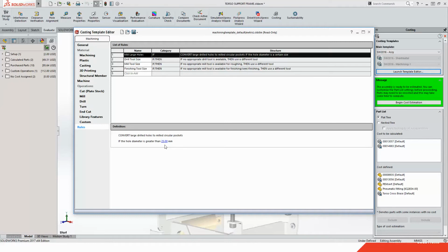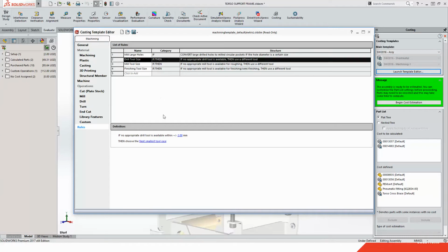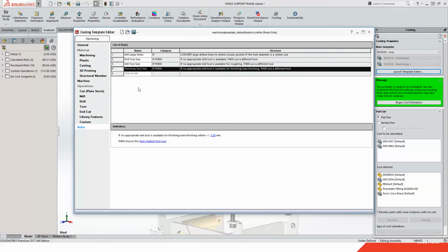We don't really have big drills that size, but we are going to go ahead and hog that material out with a mill and finish operation. Drill sizes, we want to go ahead and take ones that are within a particular distance and go to the next smallest in the tool crib in this case, and so on and so forth. These are those types of things that are always applied within your business.